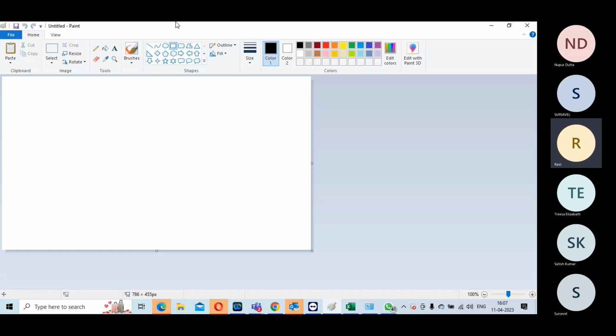Correct. So you want to aim for a critical net, like a key net which is crossing. There you try to use shielding. What is the problem with shielding? What is shielding? Shielding means on either side you will use ground or VDD. This is the one preferred to use. If you are adding ground, that means you are adding capacitance, ground cap. Yes, it will avoid any crosstalk. If you added shielding, there's no way crosstalk can happen on that.